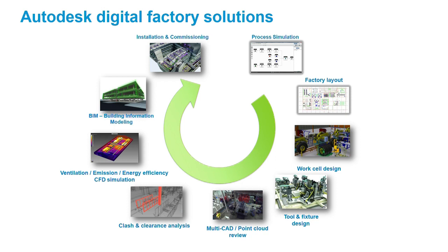Actually, the factory design utility basically allows you to use the, I think, well-known AutoCAD block concept, but to use it in 3D. So basically, you have your assets that you can snap together for rearranging any layout, so not necessarily a factory, an assembly, a production layout.